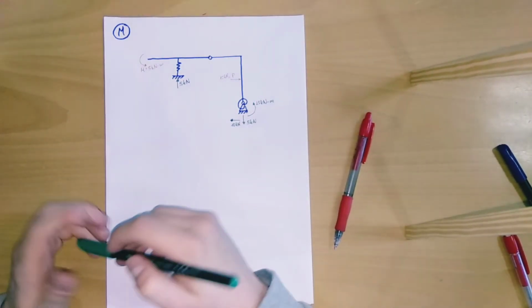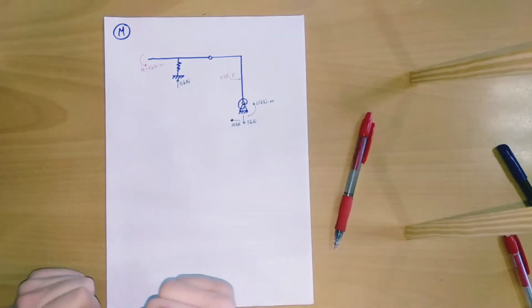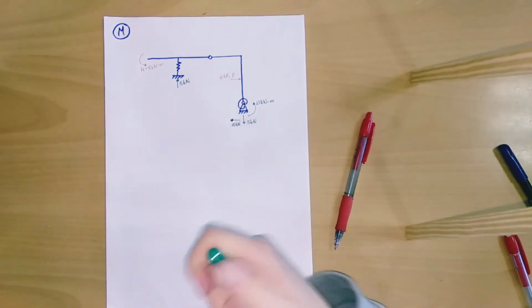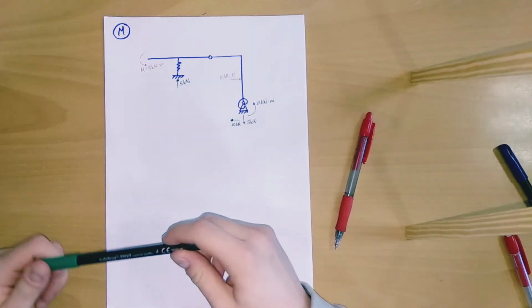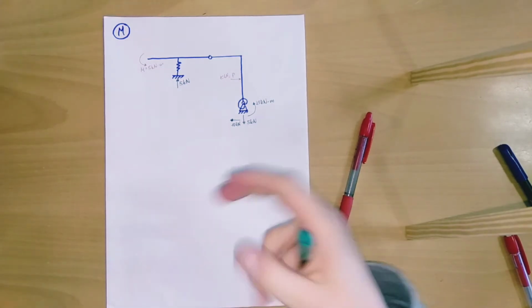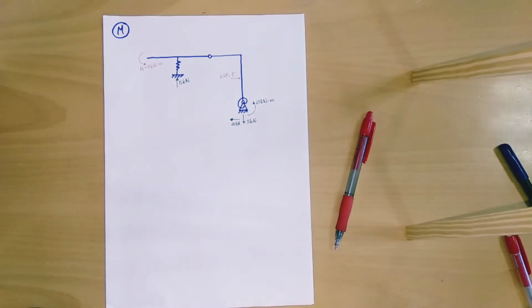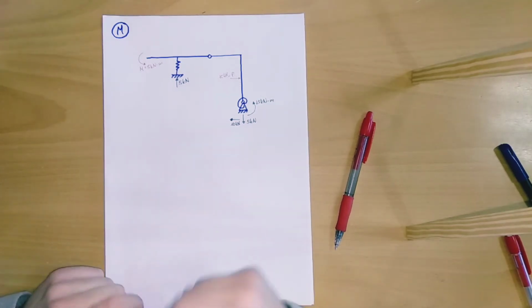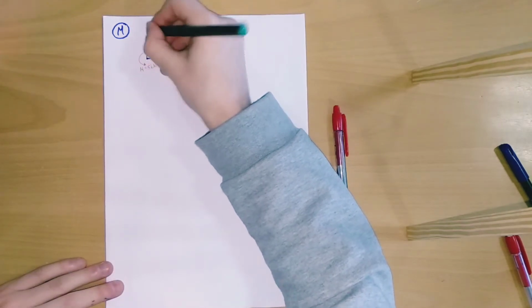Well, we are going to start by reminding the way of calculating a bending diagram. In this case, we're going to put the bending diagram in the upper part when the part of the beam under tension is the upper part, and in the lower part when the part under tension is the lower part. At the beginning, we have an anti-clockwise moment, which is going to cause a jump in the bending moment diagram, of value 5